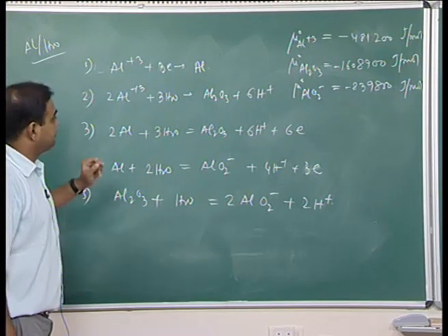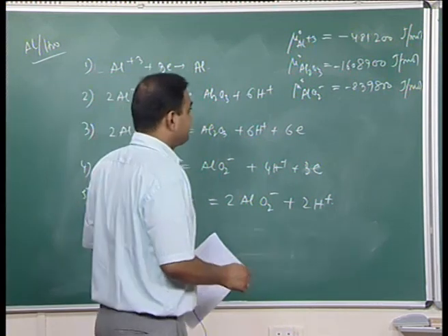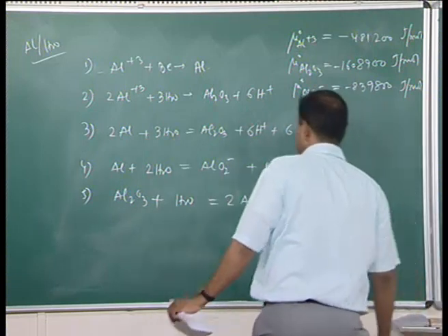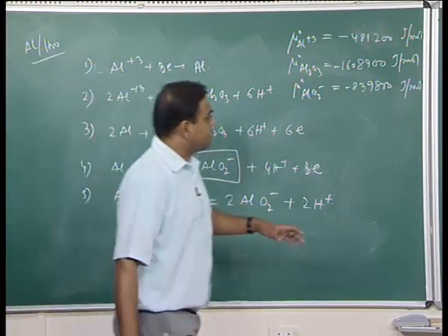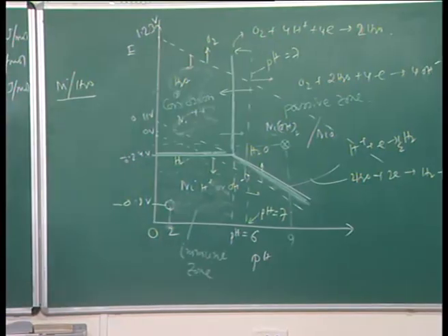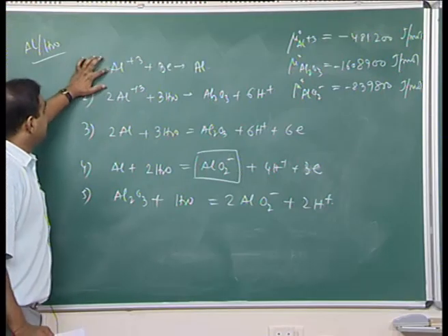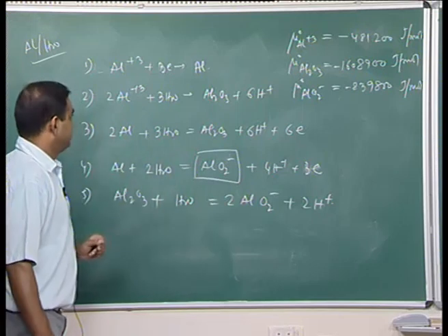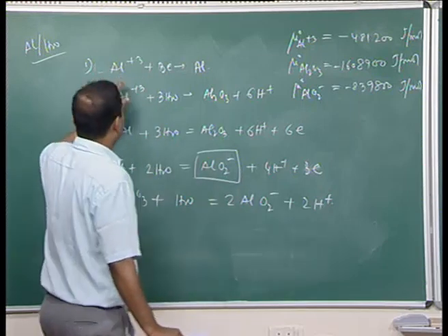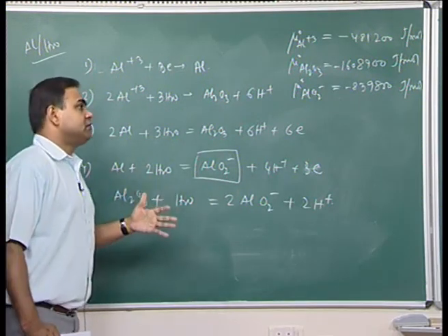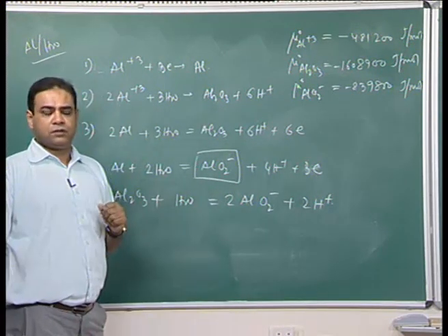So, if you do the same operation, then you also get a Pourbaix diagram for aluminum system, and here the interesting part is this ion, because in nickel system we have Ni++ ion only with the information we had, but here you have two ions, Al3+ as well as AlO2-, and whenever we have a metallic ion, whether it is a complex ion or a simple ion, if the metallic ion is going in the solution, then always it would be a sort of dissolution.